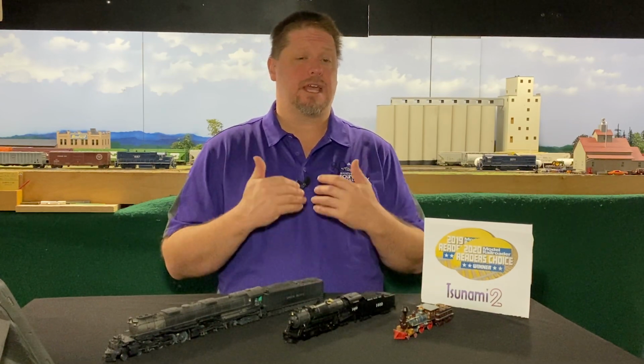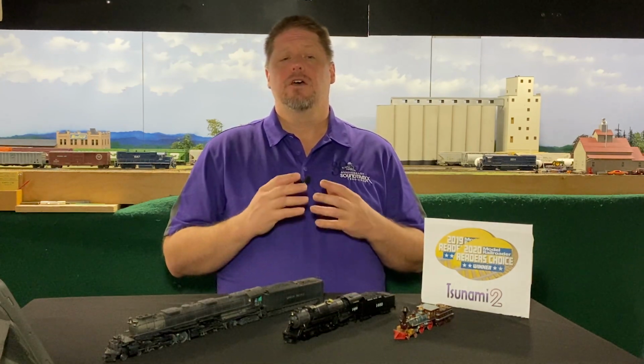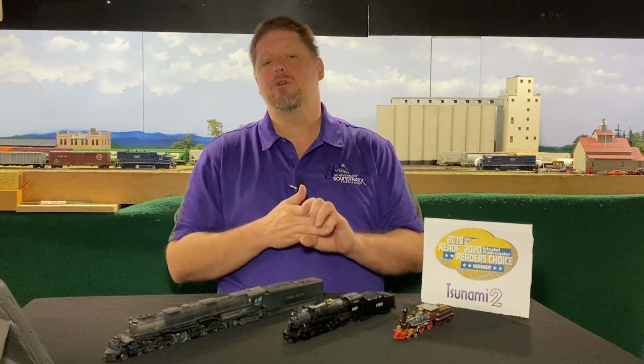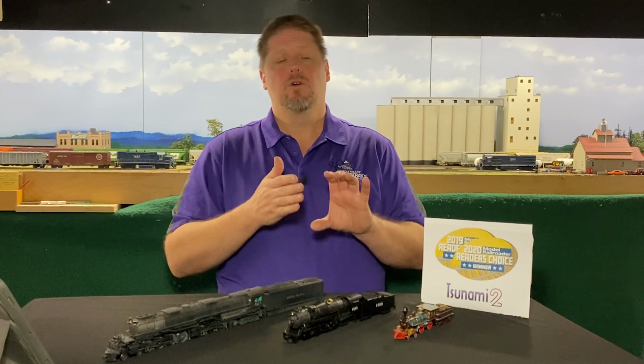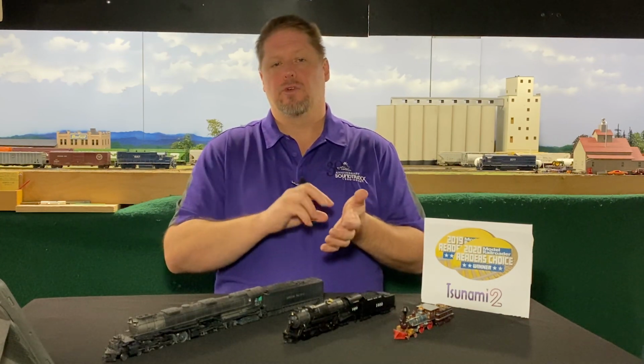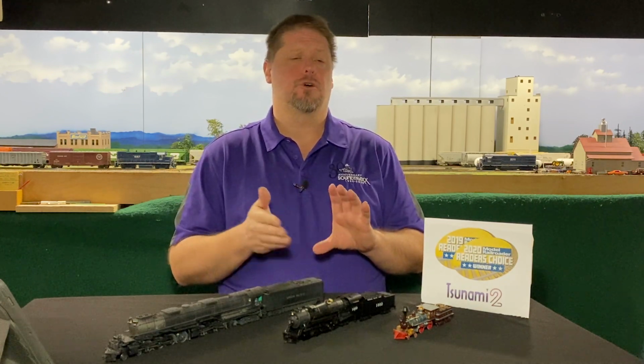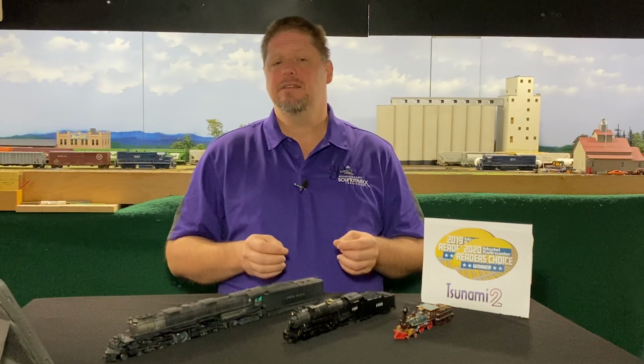So our engineers went to work and they decided a better way to do this was to do a digital cam based on the rotations of the motor. So now when you set your chuff rate in CV114, the decoder is able to identify rotations of the motor and keep your locomotive chuff in time with the rotations of the motor to make sure that no matter what speed you're going, your chuffs will always be in time regardless of your commanded speed step. Now this is watching the back EMF of the motor, so be sure to set that up, then set your chuff rate and get everything dialed in and you'll be really